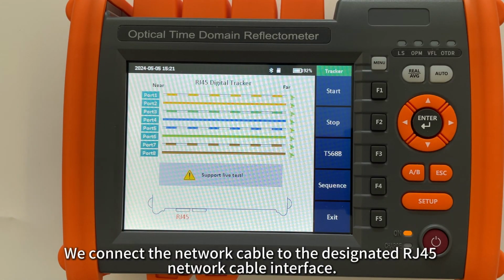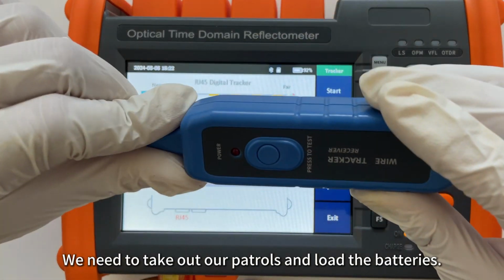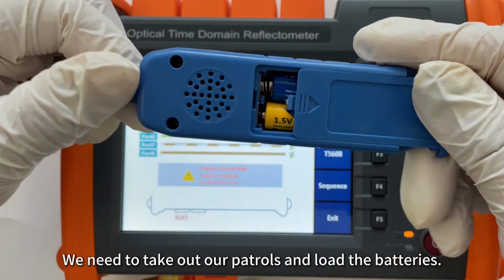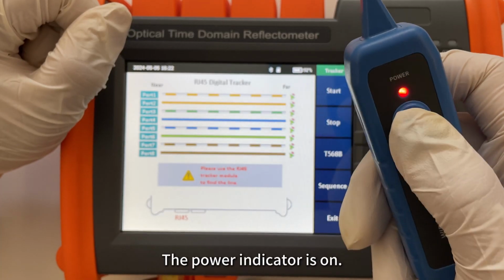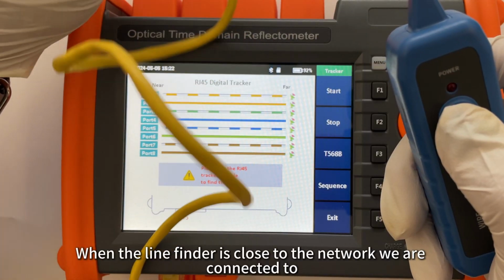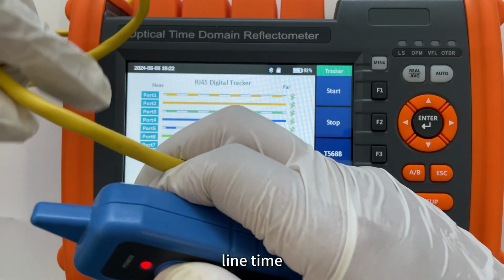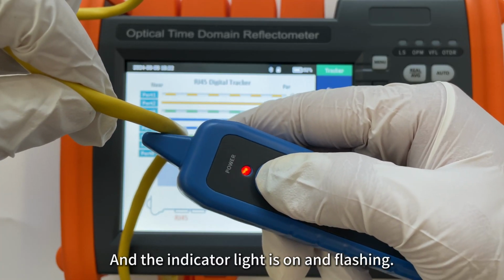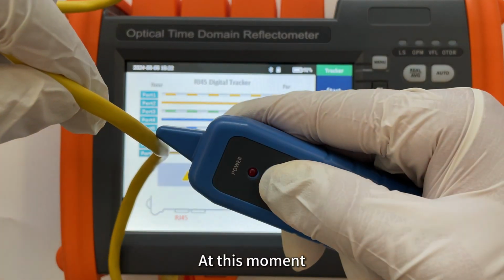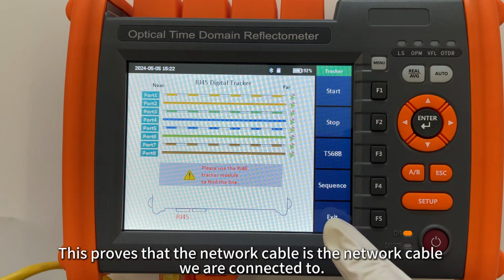We connect the network cable to the designated RJ45 network cable interface. Click to start. We need to take out our line finder and load the batteries. Now press and hold the switch on the line finder. The power indicator is on. When the line finder is close to the network cable we are connected to, the line finder will beep, and the indicator light is on and flashing. At this moment, this proves that this is the network cable we connected.